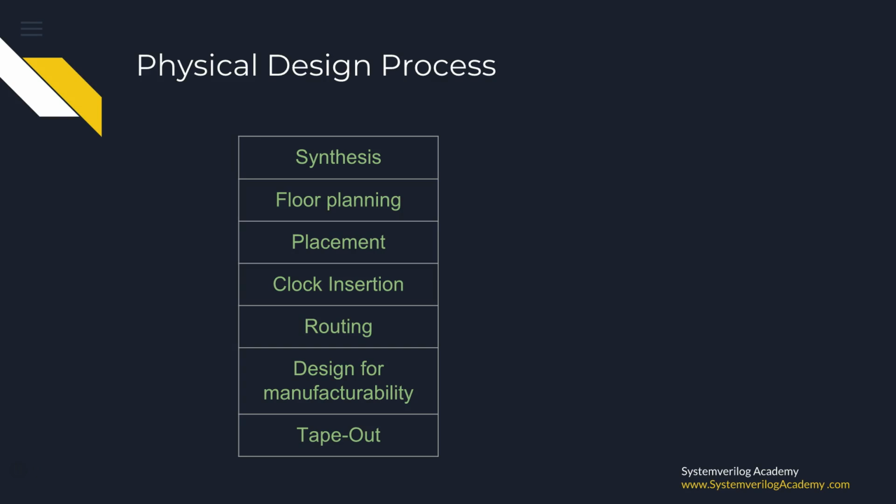Till this point of the physical design process, you have decided the position of all blocks in the IC and the position of each logic gate of the circuit in the silicon as well. Obviously, the next step is to connect these gates according to the circuit diagram, which is done in the routing phase. Routing, or wire routing, is the process of connecting different components placed in the circuit appropriately using metal wires. To understand the placing and routing phases in the process, you can compare them to the same steps in PCB design.